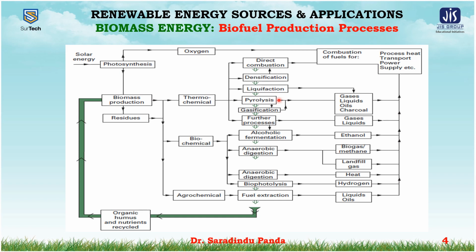Best results come from dry wood burning in a stove, oven or boiler with control of the incoming air, so that there is full but not excessive combustion. Air entry is needed around the fuel for initial combustion and into the hot exhaust for the secondary combustion.